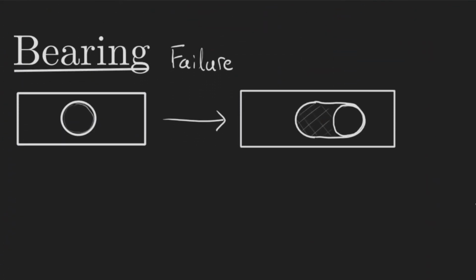The idea here is that if I have essentially some slot right here with a pin going through it, so if you imagine this in 3D, we kind of have like a little pin right here, right? Coming through and kind of projecting through it like this, where this right here is our hole. And there's a force being acted onto the slot by the pin, and if it fails, if it yields, then it can kind of stretch through it like this, right? So basically what we'd have is if we looked at the little circular area of our bearing pin, we would have something like this, and it would have some thickness. So it would look a little bit like this. This isn't the greatest drawing because it's like a curve in 3D. But you see what I mean?